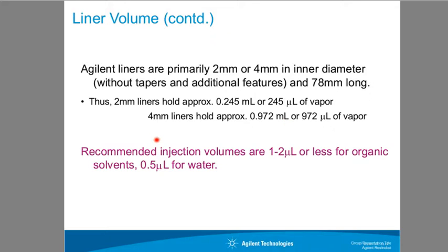They're either going to be 6.3 millimeters on the OD or 6.5, depending if it's split, which would be 6.3, or splitless, which is 6.5, because in splitless mode the key is to get all the sample onto the head of the column, so we want to really occupy the whole inlet if possible. The 6.5 millimeter OD liner does that a little more than the 6.3, which provides an easier flow path for the split flow to go back out the split vent.